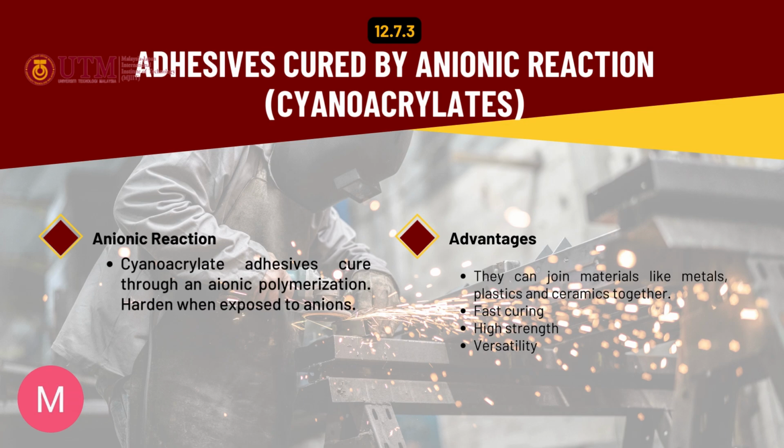For adhesive cured by anionic reaction, cyanoacrylates. Cyanoacrylate adhesive cures through an ionic polymerization, hardening when exposed to anions. The advantage: they can join materials like metals, plastic, and ceramics together, with fast curing, high strength, and versatility.